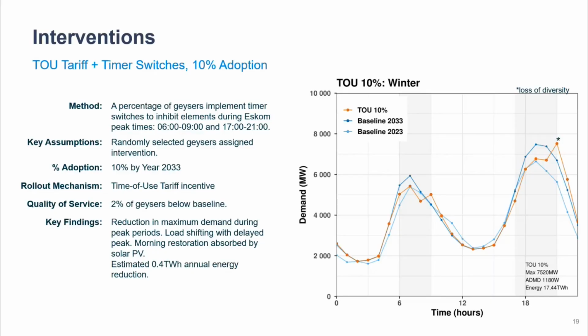But there's this unintended consequence, and this is, again, that conservation of misery. We have a total loss of diversity when all of these elements now switch on at the end of that interval. Now, we haven't tried to be smart and put in stochastic. We've just said, right, at the end of that period, they all switch on. So maybe one could be more clever about how they switch on, but I think there is an important lesson here. And this is very reminiscent of what would happen at the end of load shedding when power was restored and everyone's batteries all started wanting to recharge themselves.